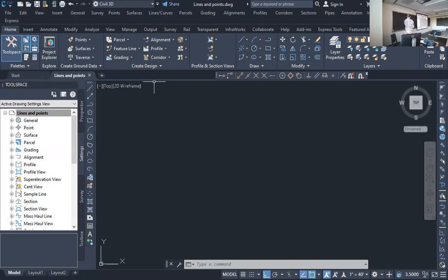Okay, so the 2 line commands that you need to know are drawing lines by coordinates and drawing lines by turned angles. Okay, that's pretty much what you did. So everybody should have located the benchmark between Pardee and Colburn, right? You should have coordinates on that. And somehow you should have closed back to that, right? Or closed your loop. And you should have coordinates on the spire. And we're going to talk about how you get the X and Y on the spire of Colburn Chapel.